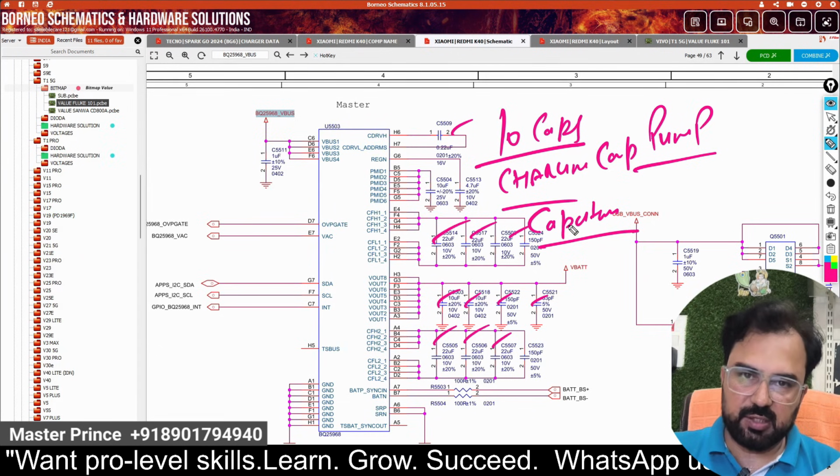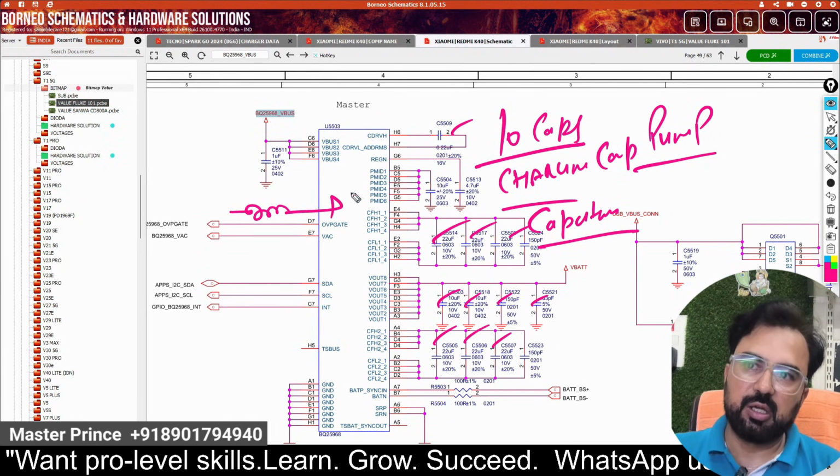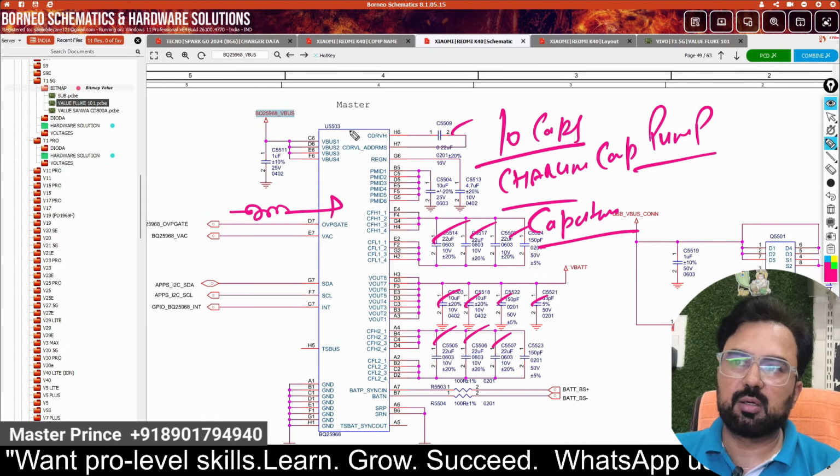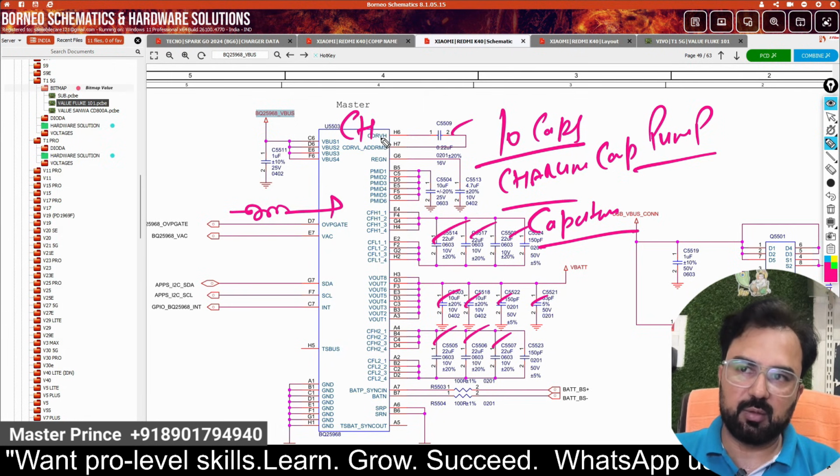Basically in the main charging IC, you see there is a coil switching with the MOSFET and the boot cap, after which the high ampere is generated. But this IC, for generating the high ampere, switches with the capacitors. So we call it pump charging, capacitor based pump charging.